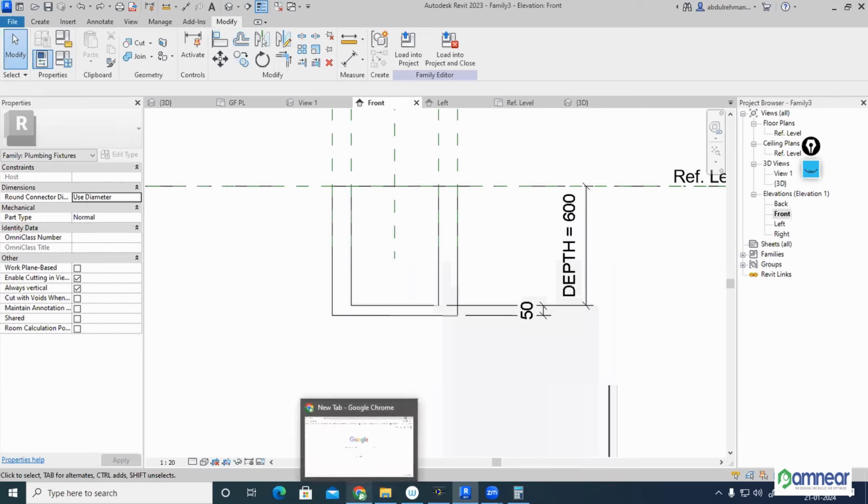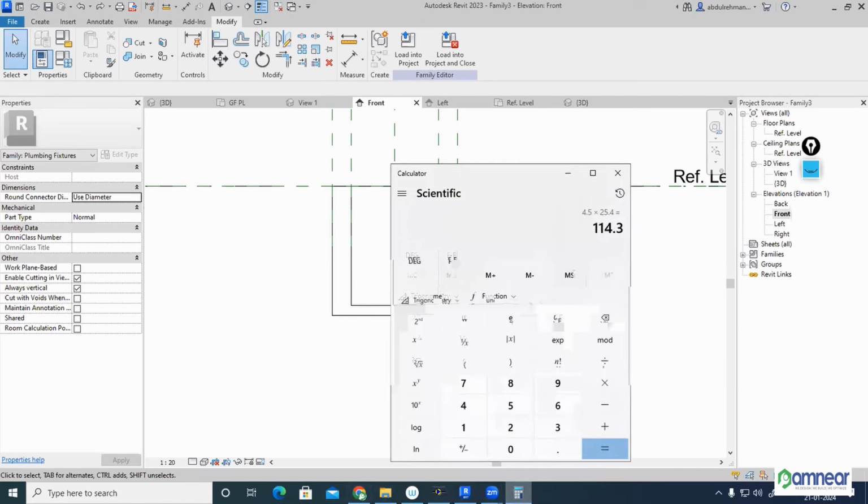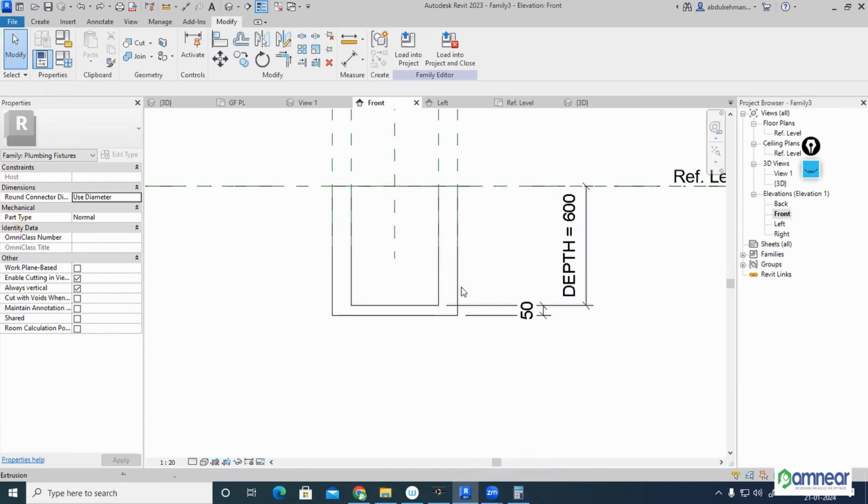Or you can go to the schedule 40 PVC plastic millimeter chart. You can Google it simply. Or any pipe chart you can check, you will be getting internal dimension, external dimension with respect to the schedule. Nominal pipe size or nominal diameter, you'll be getting the value in millimeter. Anyhow, I need 114.3 divided by 2, 57.15. So this is my outlet and this is my inlet. Means, let's say my pipe will be entering through this way and my pipe will be leaving from this way.